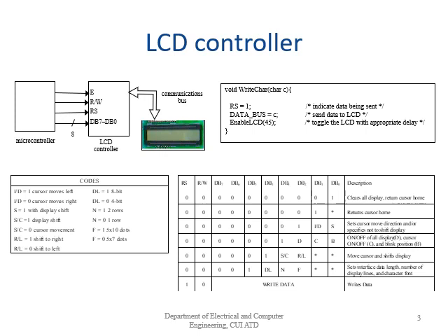So in this first slide, you can see that we have a microcontroller. The enable signal is coming from the microcontroller, the read-write signal is coming from the microcontroller, and then this RS signal is coming from the microcontroller, and then the 8-bit data is coming from the microcontroller to the LCD IC, which is interfaced with the LCD screen.